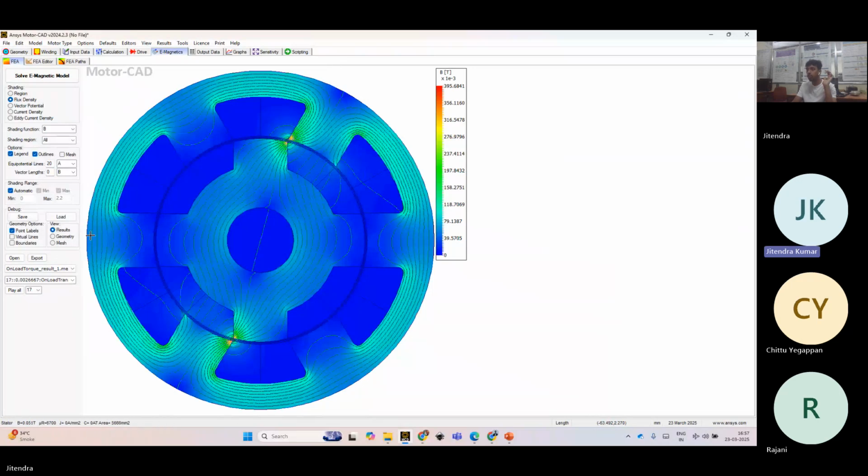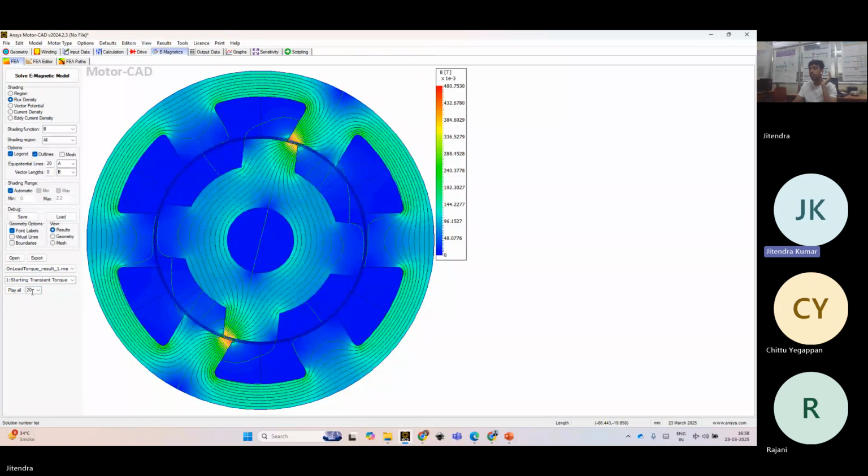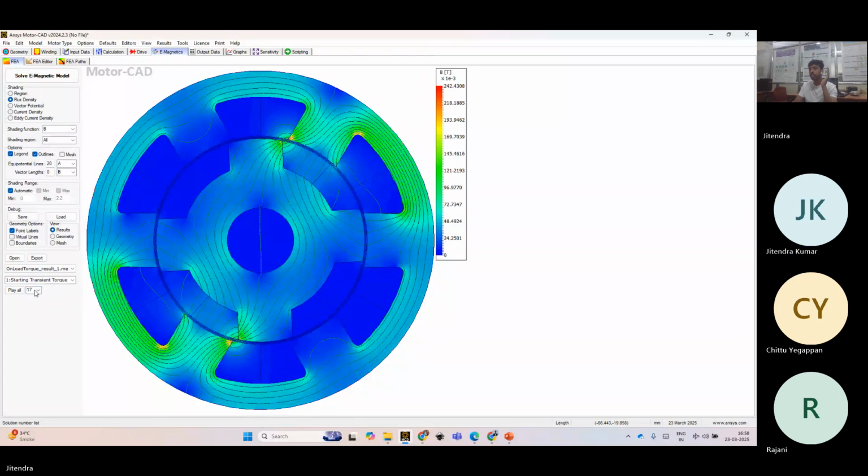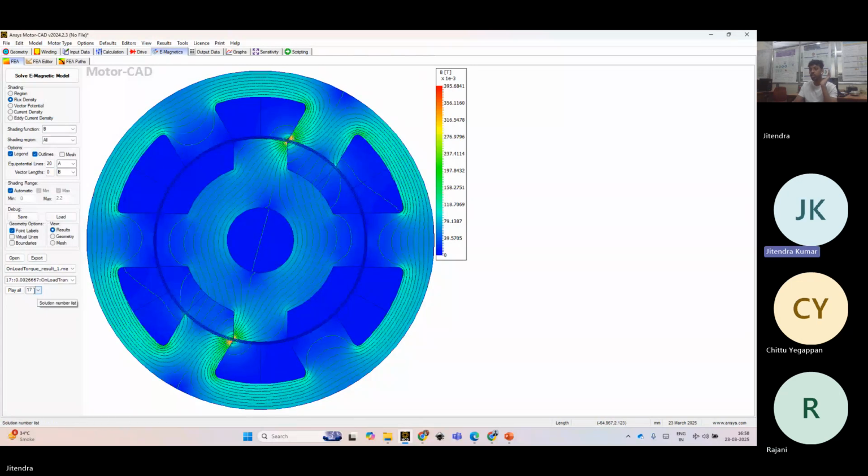And one rotor pole is completely aligned to pole B, so that is not going to produce any torque. Now the poles which are completely unaligned are these poles. These poles will attract toward phase C, and see what happens. The linkage will start with phase C. Phase C will turn on at this instant only.